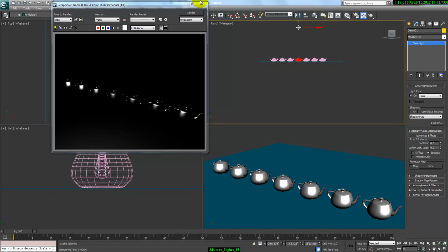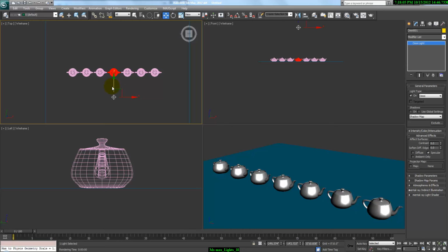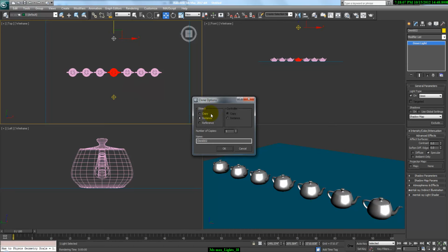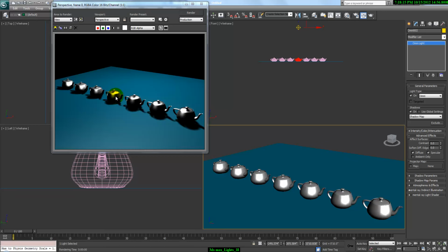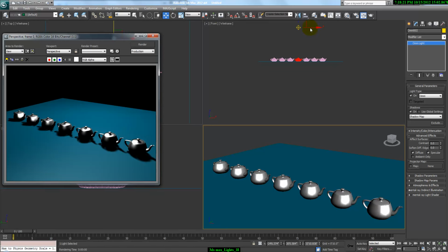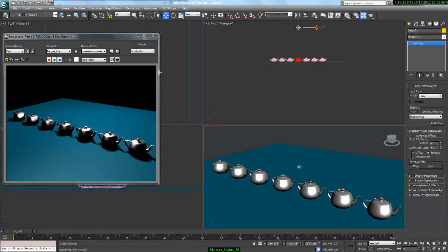If I have another light, just make a copy of this, and that other light also casts shadow. You can see that here I am having the highlight, but I am not having the illumination of this object. In the same case, for my selection, I select this and I say diffuse. Now it will render it in another way.